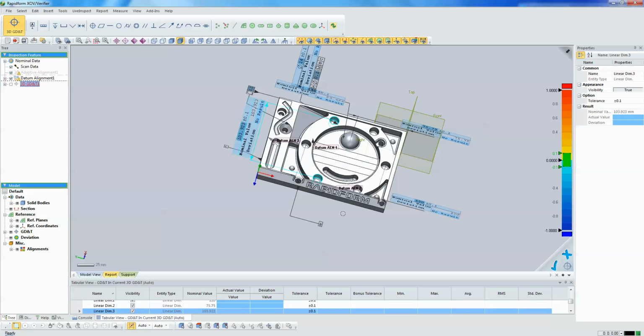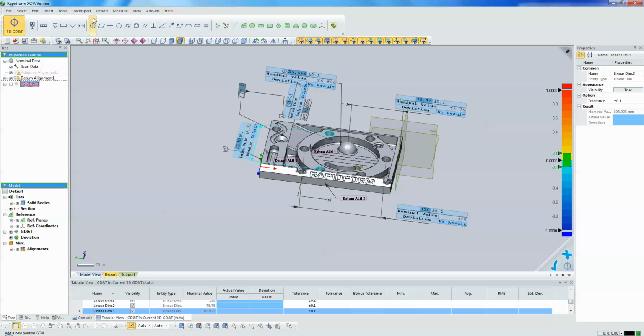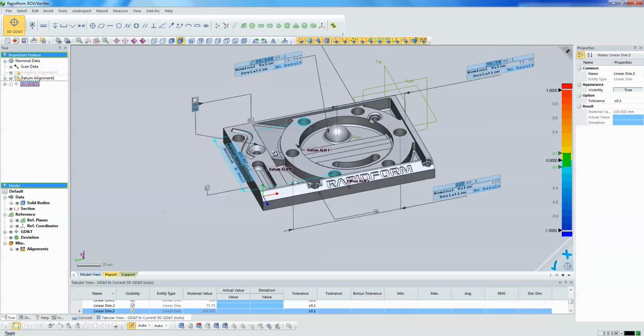Again, our GD&T is totally up to date with the ASME Y14.5 2009 standard. So we can add any of these tags where relevant. This is a manageable amount of GD&T to show a customer in a short period of time. A few dimensions, some that are overlapping, so measuring the feature will help build several tags. And I've already built off of some things that I've already measured.